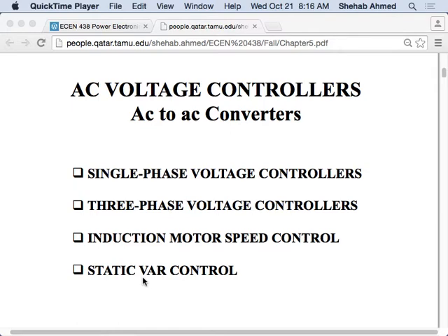But placing these capacitors in the power system can be done using simply a capacitor and a switch. Whenever the power factor is too low, meaning there's too much lagging power factor, or too much reactive power being pumped into the system, you add some capacitors, and whenever you see the power factor needs correction, you switch the capacitor into the system. That works fine. Again, we don't want to operate this power system in leading power factor.